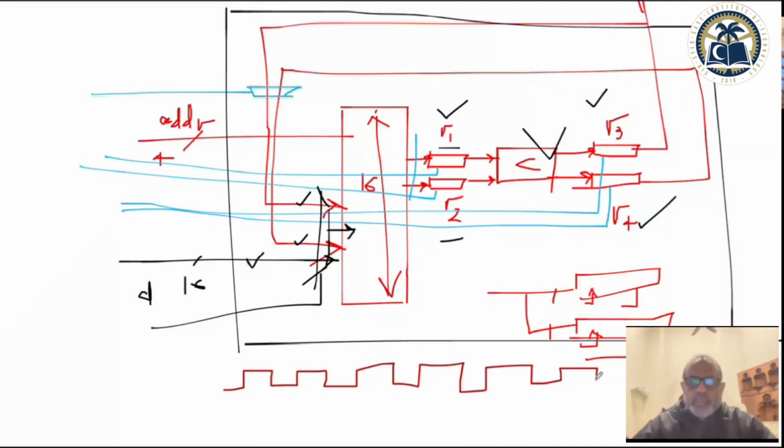So you have to plan that first you need to, for example, read a value into the R1 register in this clock cycle. Okay, and because you need two values to compare, you read another value in this clock, the R2 value. And once you have R2, this will do the comparison and you have the result of the comparison.